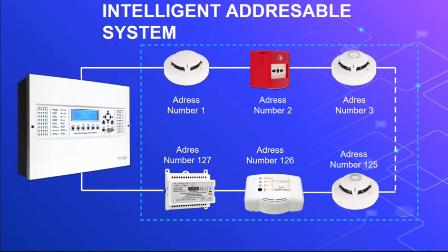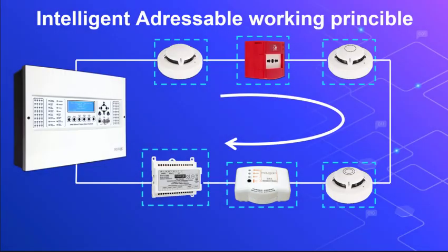In addressable systems, devices are connected to the loop line of the addressable control panel. The loop line exits the addressable fire alarm panel, and the addressable devices are connected along the line. Finally, the loop line returns to the control panel. All addressable devices connected to the loop receive separate addresses either mechanically or by software. In addressable systems, the devices connected to the loop line are queried at certain intervals. Error and fire situations occurring in the system are reported to the fire alarm panel as points.